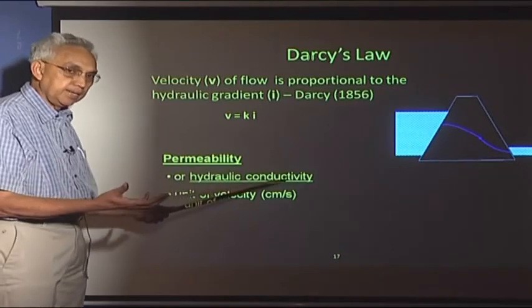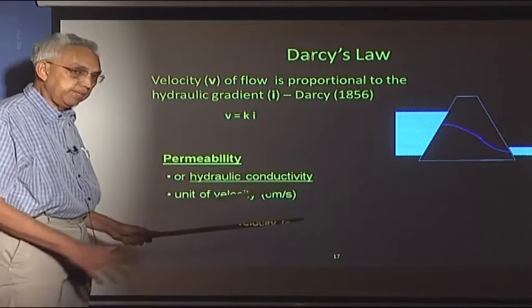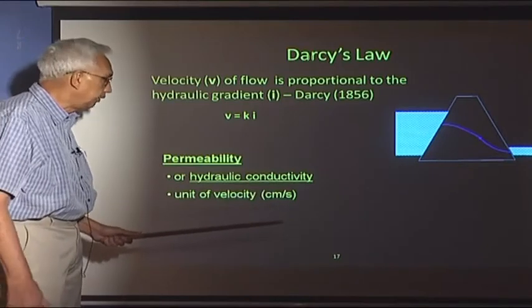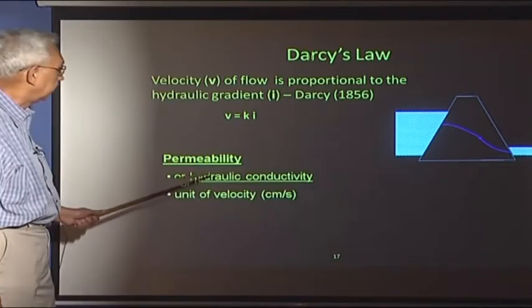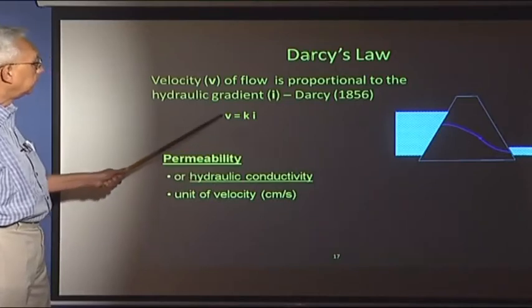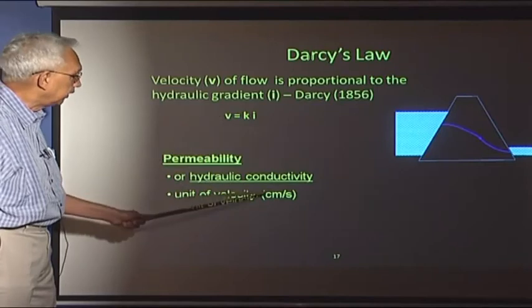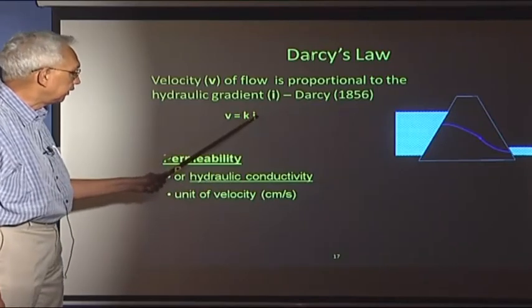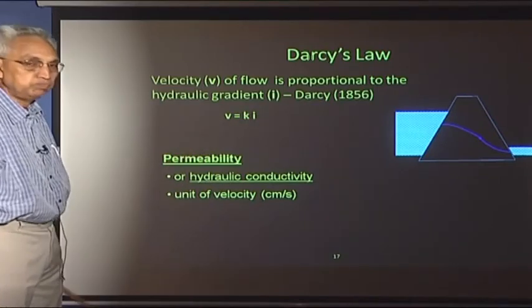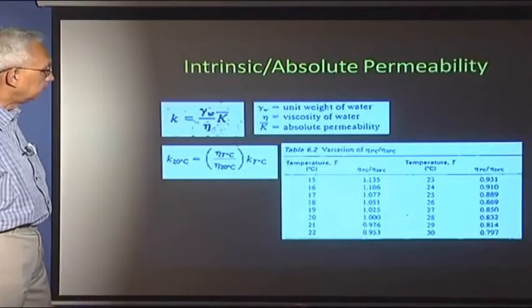It's like electrical conductivity or thermal conductivity. To keep in similarity with other phenomena, we also call it hydraulic conductivity. The units are velocity, so V is centimeters per second, i is dimensionless, so K has to be also velocity. These are some of the values.